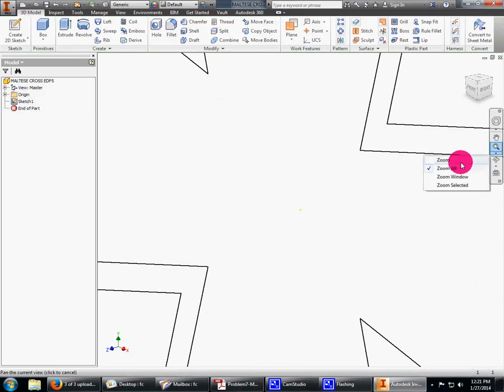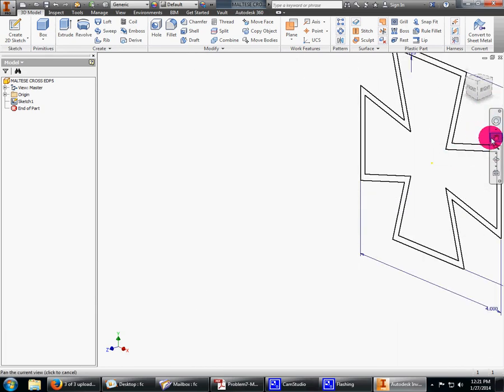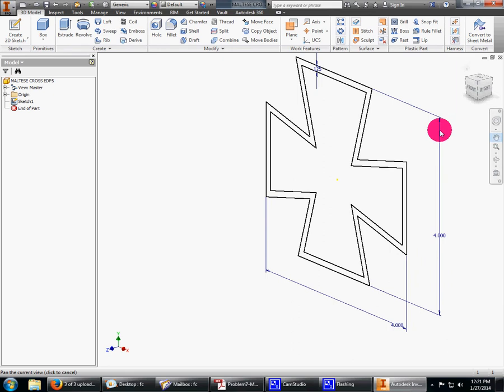and let's do a zoom all. Come here, you. And don't panic when it does that because this is normal. It automatically does this. It's like a presentation view. Don't panic. And now we're going to create an extrusion, so we're going to make it 3D. And we want that extrusion to be 1 inch coming out.